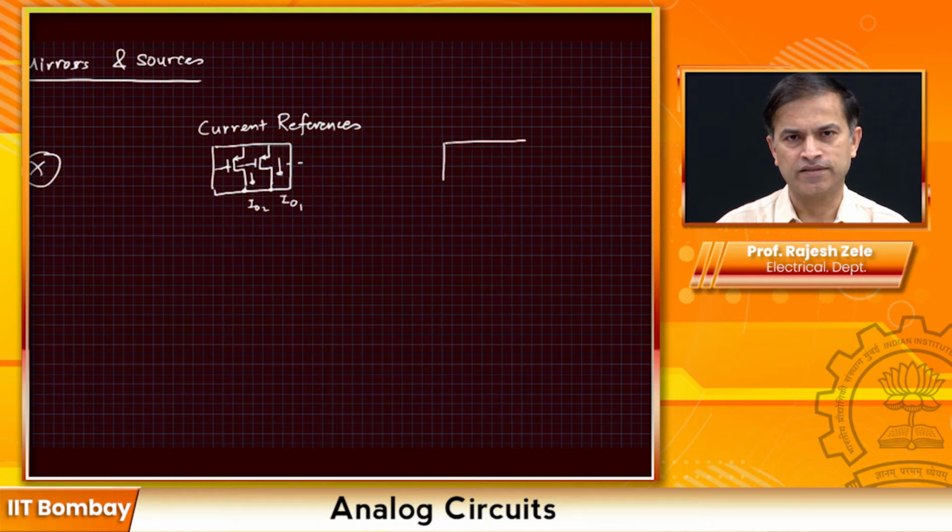Here you could have a block on the other side of the chip, far away. You could have a block called a current mirror, which will take that current and mirror it locally, giving you multiple copies of the current. Keep in mind that transistors match very well when they are laid out properly and are next to each other. However, as the distance between them increases, the matching gets worse. That's the property we need to keep in mind.